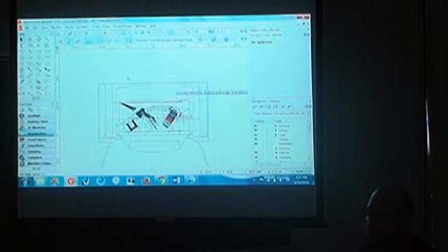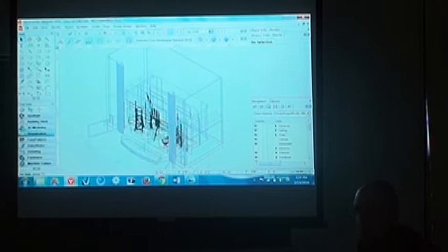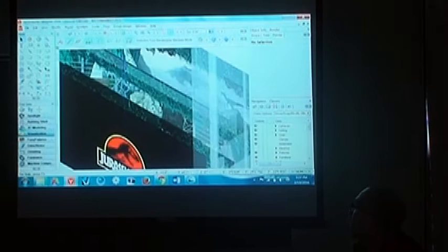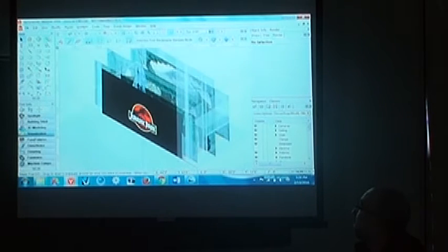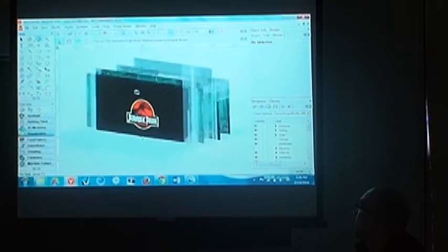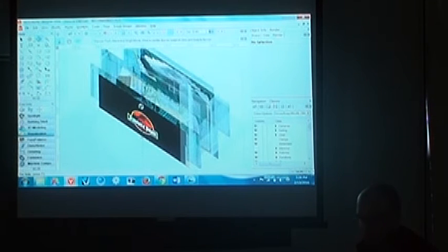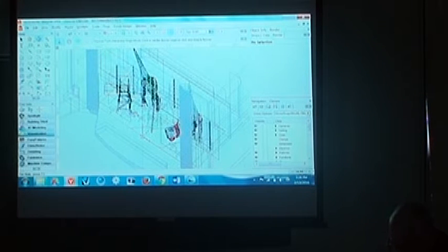You could also use a camera object. If you placed a camera object, you could always go back to the exact same camera that way. Render shortcuts: Control-Shift-W gets you to wireframe. Control-Shift-G gets you to OpenGL. OpenGL is probably the best mode for still being able to deal with your model and have it rendered. It's not going to take a long time to reprocess when you're moving things around in OpenGL. Control-Shift-W back to wireframe. Control-Shift-F will give you final quality RenderWorks when you want to really let it process things realistically.